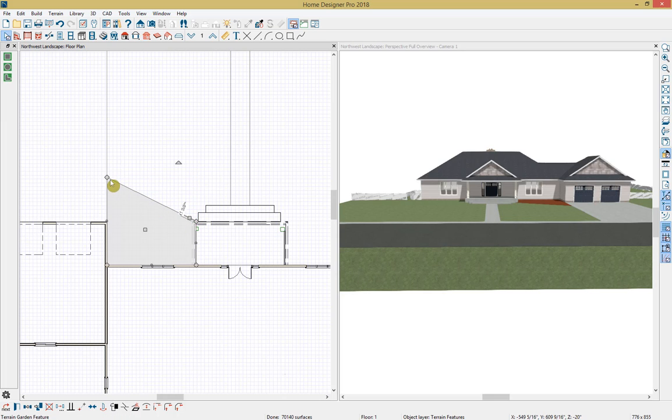like so. And one more change that I would like to do is to edit this to be an arced line. So I'll grab that line, and down here in my bottom toolbar I have this change line to arc tool, so I'll select that. And now that it's an arc, I have some specific edit handles. I can reshape the arc or resize it, and I can also change the angle.